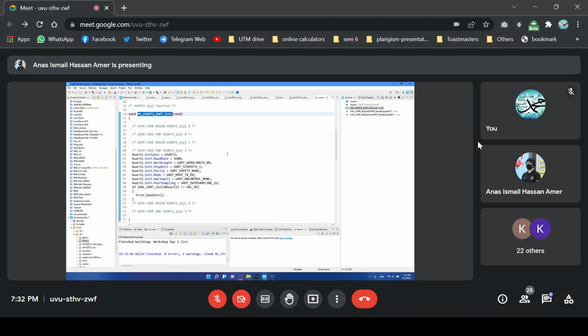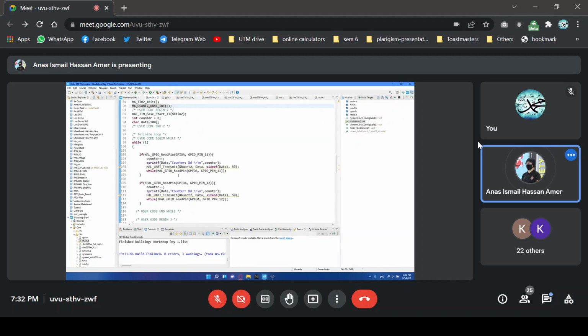All right. So, any more questions regarding the code? You can see there's a warning. There are 2 warnings. This is because your transmit expects an unsigned int. So what we can do is cast this data. An unsigned int is also 8 bits, the same size as character. But if we ignore the warning, it will still work. So we can just cast it to remove the warning. So this casts data.